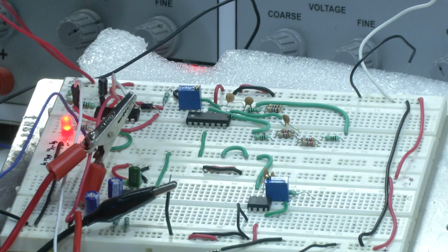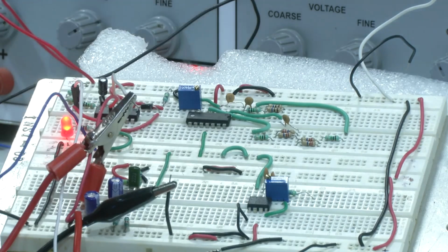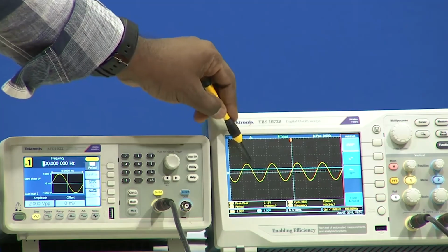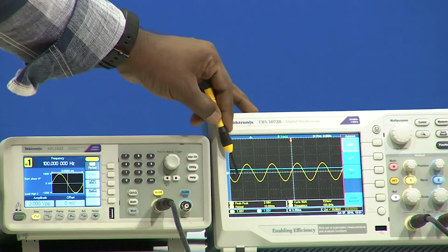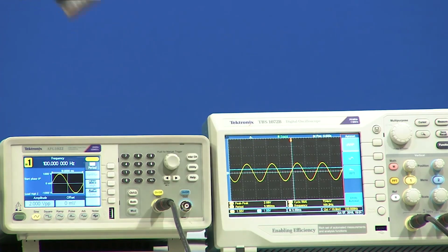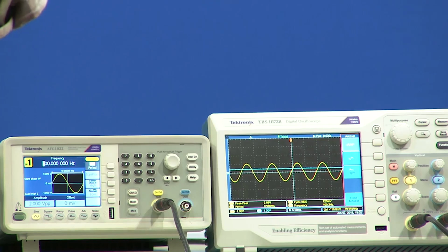So we have connected an output at this point, which is the combination of 1 mega and 2 mega resistor. Here if you can see, we have applied an input frequency of 100, amplitude peak to peak value of 2, that means a peak value of 1 volt. Now when we see the output, the yellow represents our input and the output is in blue color. The peak value is 1 volt, 1 box, and the blue color is at 2 points, so somewhere around 486 millivolts we are getting.